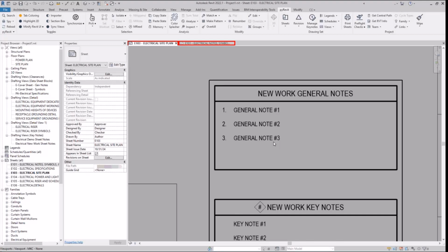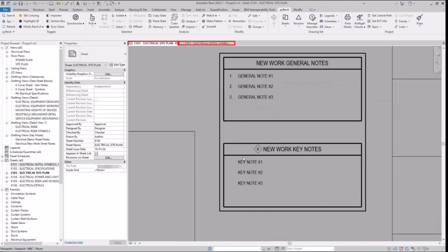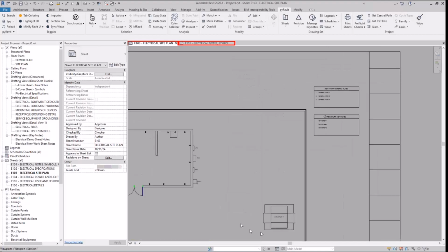That note right there always goes in the general notes on each sheet, period. Because clients hate it whenever some electrical contractor shuts everything down and they didn't know it was coming. And if there's a big hubbub, I can point to one location on sheet 1 and then every other sheet that has this. It's like, no, you should have known this one. So general notes are, generally speaking, not anything specific unless to the design itself.